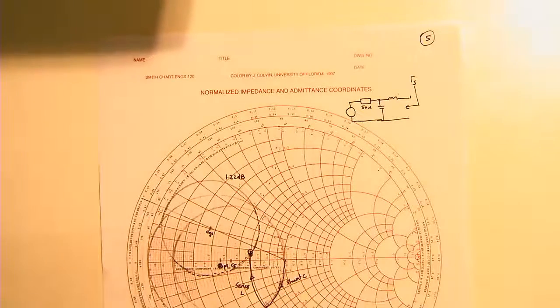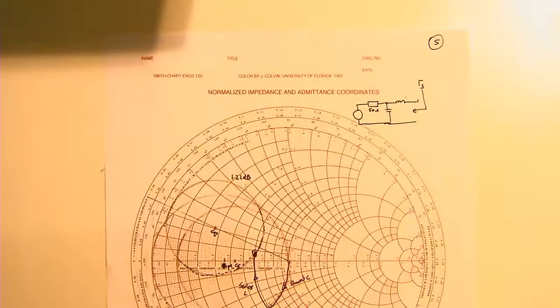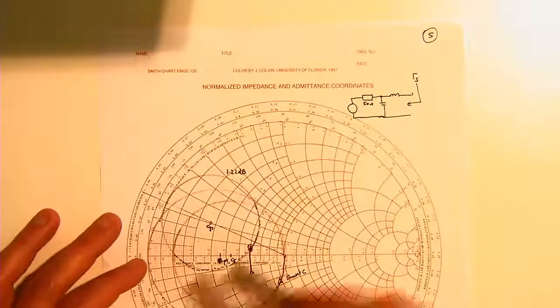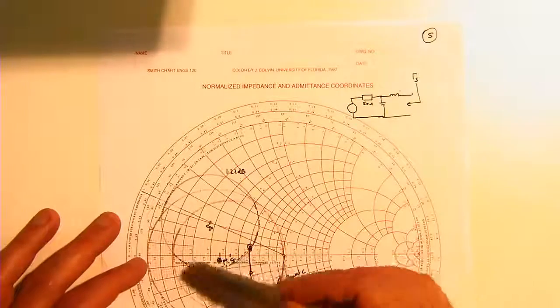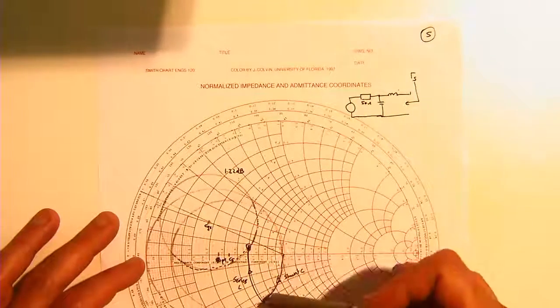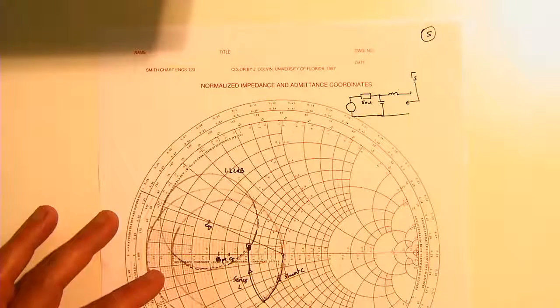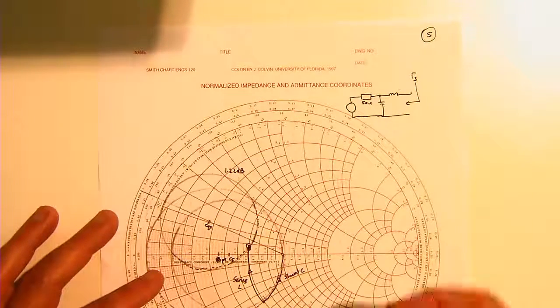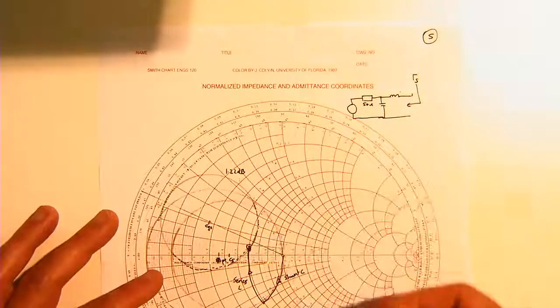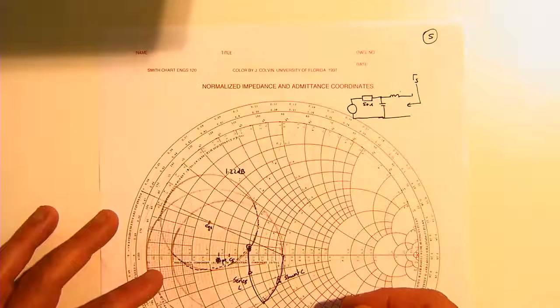And then what we said was, hey, what we want to do is work out where we are going to choose our source impedance. And what we clearly stated was, anywhere on this gain circle that is within the noise figure circle is sufficient, is appropriate, because it will achieve our gain and it will also achieve our desired noise figure. Actually, what it will do is very likely achieve a much better noise figure than the minimum that we require, which was 3.5 dB.